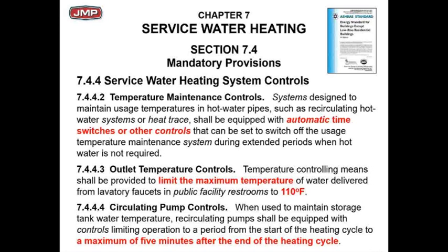Last but not least, this is circulating pump control at the bottom, and that's the one that circulates the water to the tank and the water heater. This is not the recirc pump all the way out. This is the pump that moves the water between the water heater and the storage tank. Basically it's saying after 5 minutes of the water heater turning off, we've got to kill the pump.